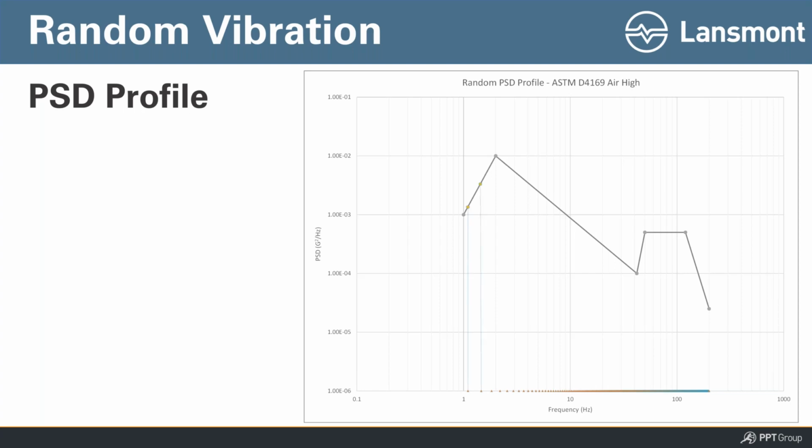What I'm going to do is draw a line up to the PSD curve, and I'm only doing it for the first 10 PSD points because nobody wants to sit and watch me do 900 of those. But I'm going to apply or focus on controlling along that line. Forget the 6 points, but think of it as the curve at this point. I'm going to slice that into individual control points along the PSD curve, whichever curve that might be. And I'm going to do math on each of those as the test is running.